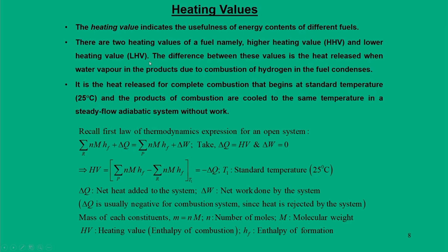Now, why is there a difference? Because the difference lies in the heat release of water vapor in the products. If you see our earlier reactions, in complete combustion reactions, there is always a formation of water. Now, if the enthalpy of this water vapor is taken into account, then we call this the higher heating value. If it is not taken into account, it is called the lower heating value of the fuel.